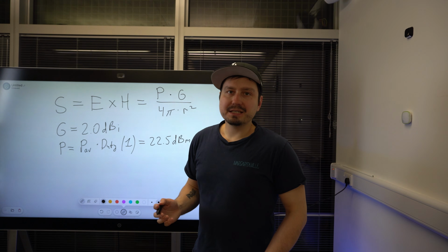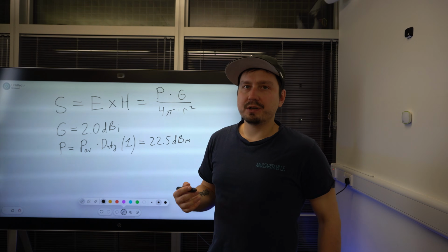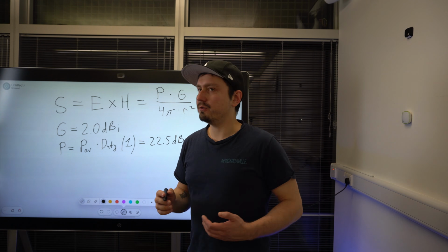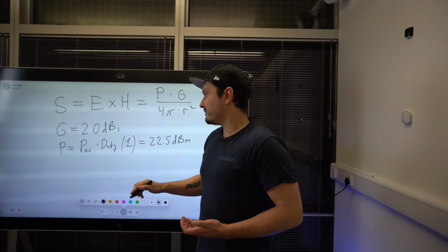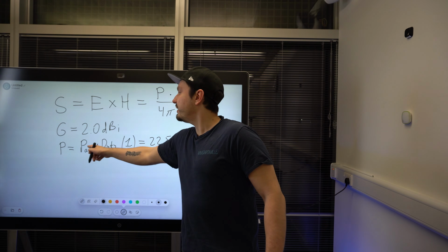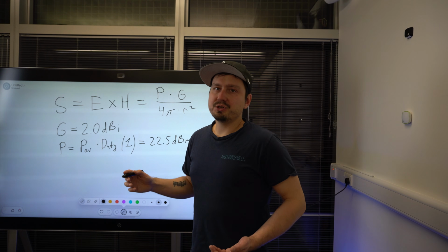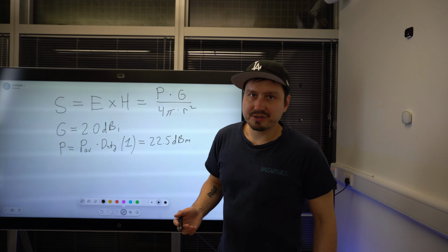However, for other bands, especially GSM, you have to use a different value for duty cycle, so you should be careful about this, because it can be 12.5% rather than 100%, but then your peak or average transmit power will be significantly larger as well.